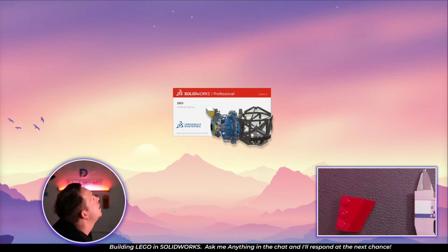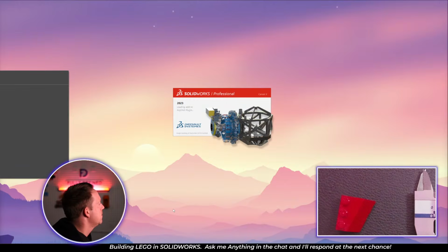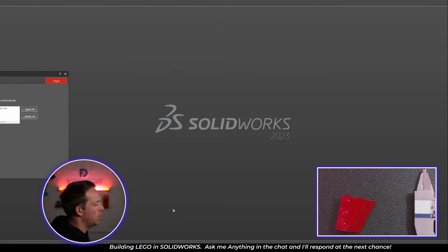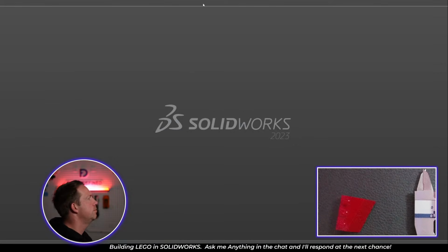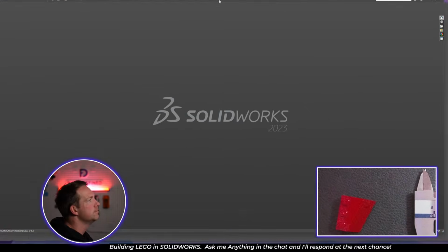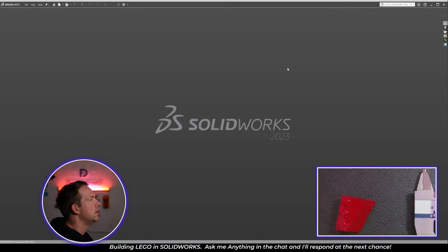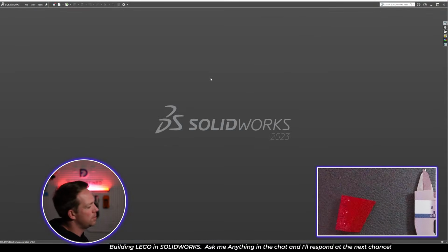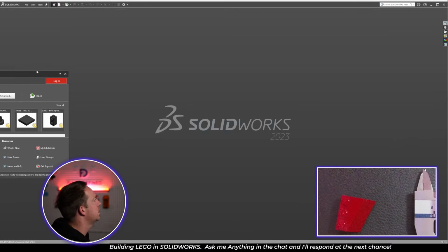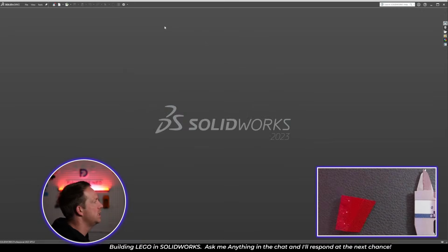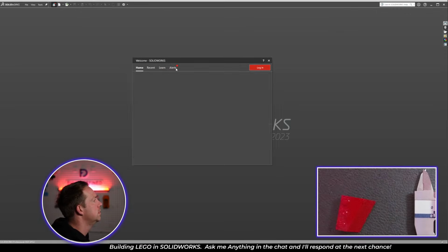So would I ever do Lego top down? I don't think so. The way that Lego's built, it's meant for bottom up, because you've got all these smaller components already done and you pull them all together. Top down is much more suited to product design where you're designing a lot of components that have shared geometry to start from.